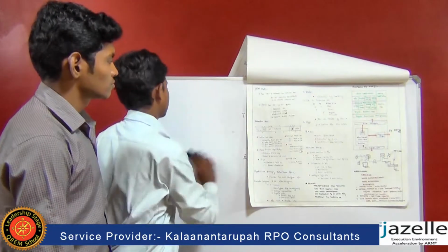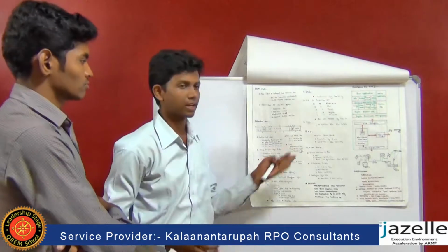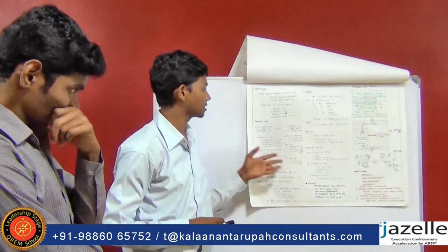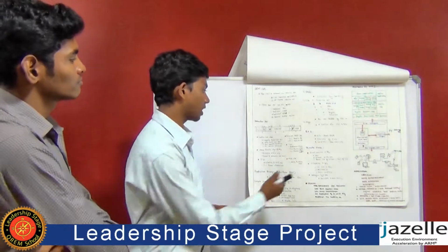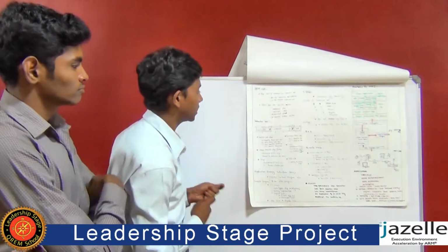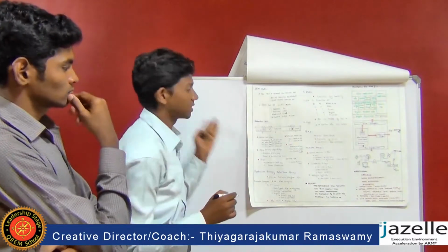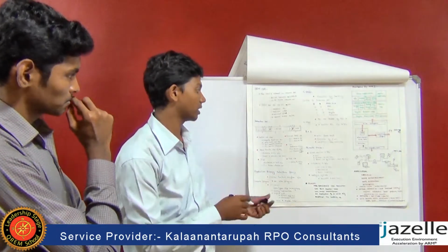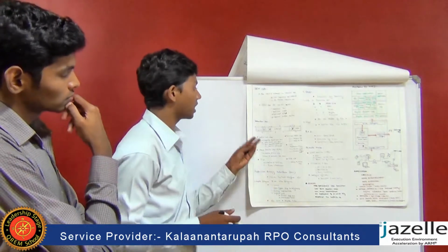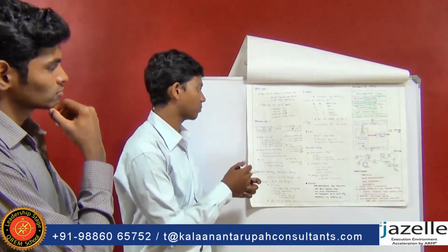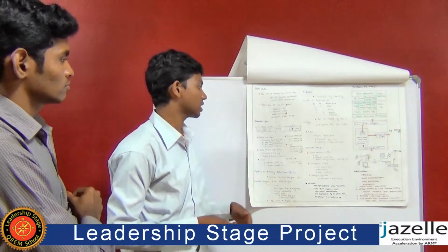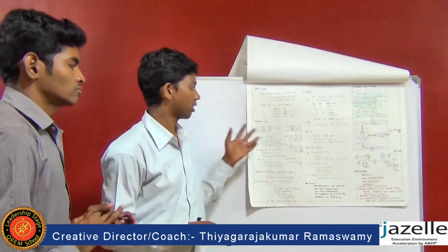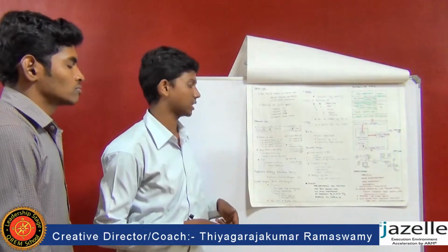Let's see about the Jazelle modes. In this Jazelle mode, there are 3 modes in this technique. One is direct execution in hardware, the second one is interpreted in software, and the third one is undefined byte code. First, we see about the direct execution in hardware. Most, 95% of the byte codes are executed in the hardware only by using the JVM instructions, and it is a common and simple program to use this technology, and it reduces the number of interpreters, and it reduces the number of JIT compilers. It is the main advantage of this Jazelle technology.